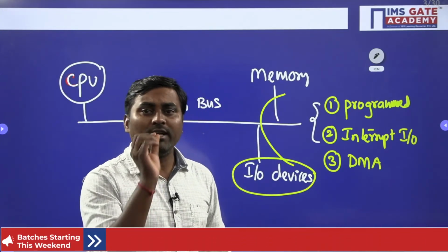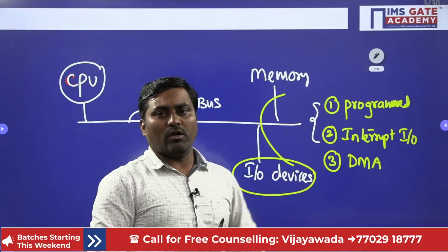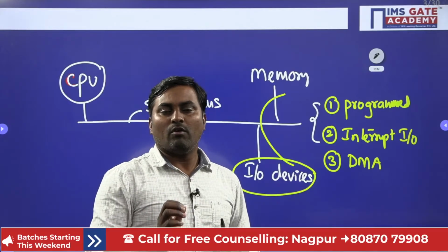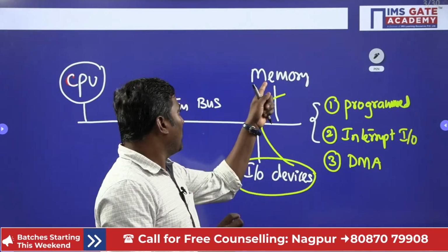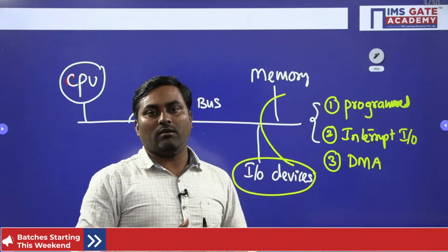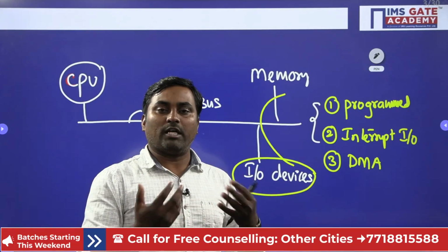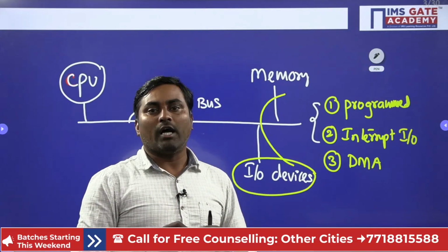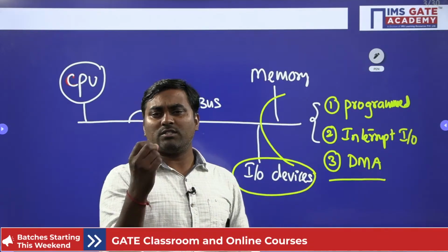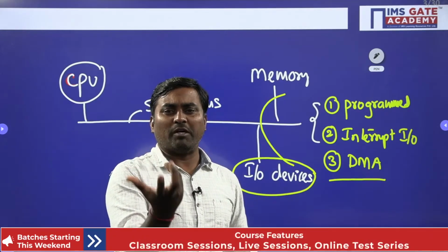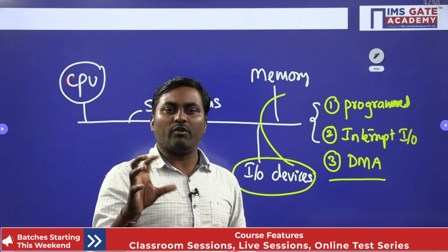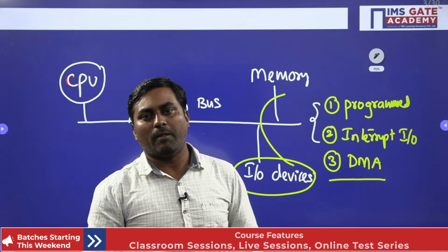When you discuss DMA, where the processor would otherwise call for the data, we are bypassing the CPU with a DMA controller. The DMA controller is special hardware that transfers data between memory and IO without the involvement of the CPU.